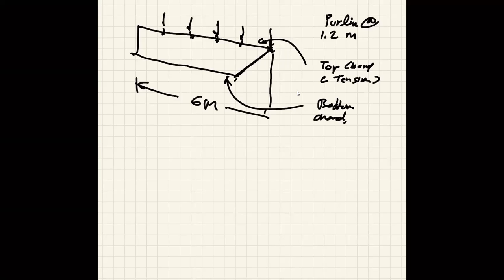Okay, and use the tube section. Okay, unfortunately for tube section, we don't have the tables. I only have the tables for H. So you're going to have to do a little bit of trial and error for yourself. You may try to treat your compression with the unbraced length that I have taught you, but since this is the tube section, the unbraced length KL on either axis will be the same.